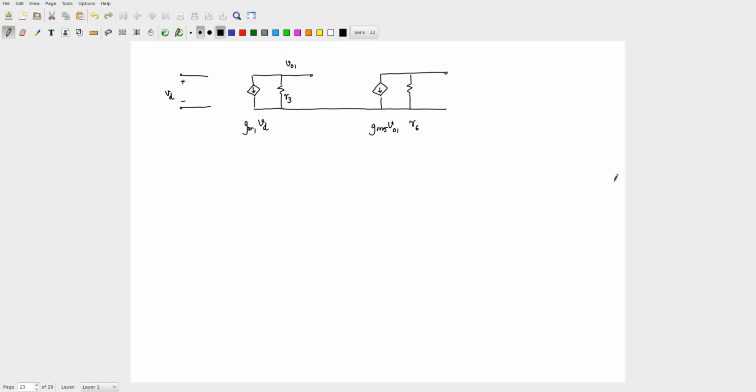So those two capacitors we will put here. I will call that C1, and just for fun I am going to call this C2. CL is your C2. Let me take some numbers so that it is clear. Let me take GM1 as 100 microsiemens. Let R3 be 1 megaohm. Let this be 1 picofarad, and similarly this be 100 microsiemens, 1 megaohm and 1 picofarad.